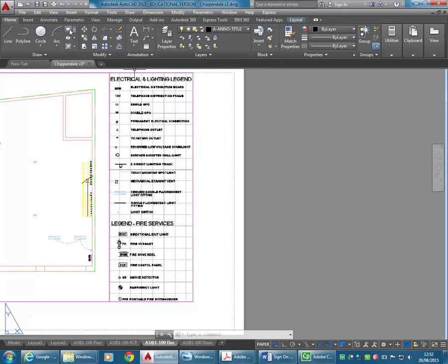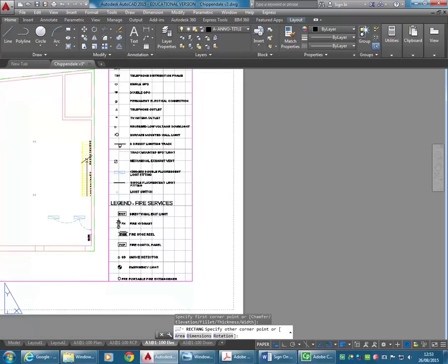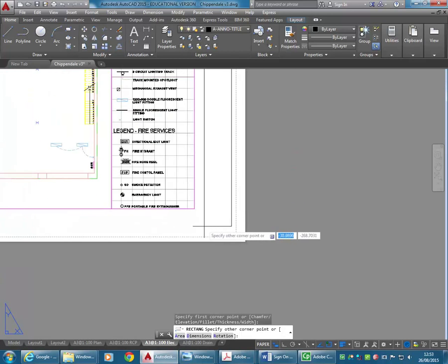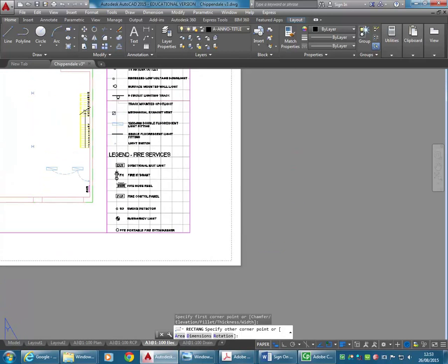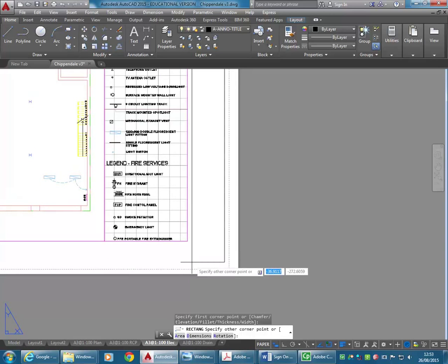And so again there with the rectangle, I'm going to draw alongside that page down the side. So 35mm across is about right. They can go up to about 50, but for A3 that's going to take up a bit too much. So 35, maybe 40mm is good.